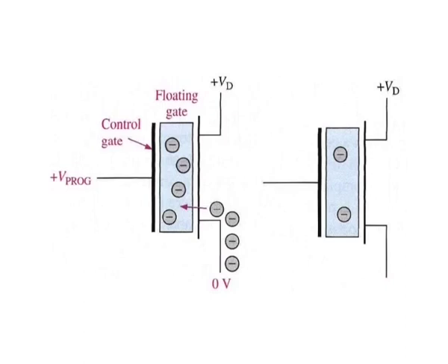The programming operation adds electrons to the floating gate of those cells that are to store a 0. No charge is added to those cells that are to store a 1. Application of a sufficient positive voltage to the control gate with respect to the source during programming attracts electrons to the floating gate. Once programmed, a cell can retain the charge for up to 100 years without any external power.